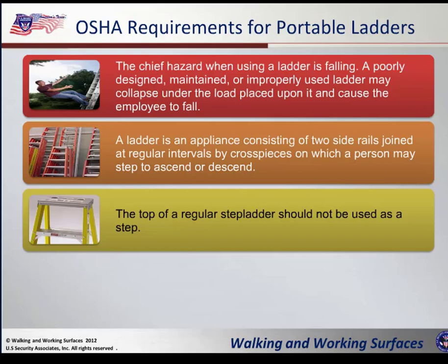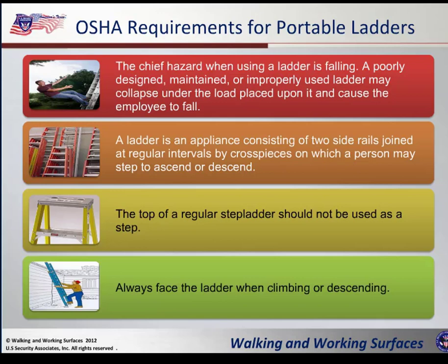The top of a stepladder is not to be used as a step. And that means that you always have to face the ladder when you're climbing or ascending. Don't go down with your back facing the ladder. Climb up and down facing the ladder.